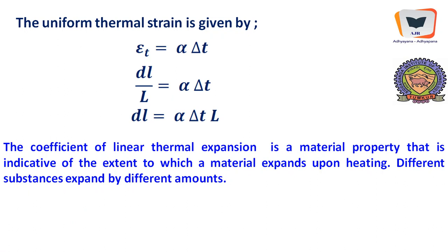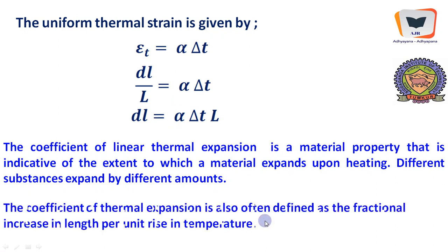And this coefficient can be measured by various methods. Among them, the predominant methods are dilatometry, interferometry, and thermomechanical analysis. Anyway, we are not going to concentrate our discussion on how exactly this coefficient of thermal expansion is measured, but we definitely emphasize that this is the material property, and the thermal expansion of material and contraction due to cooling is dependent upon this particular property, and it is expressed as so many millimeters per degree rise in temperature.